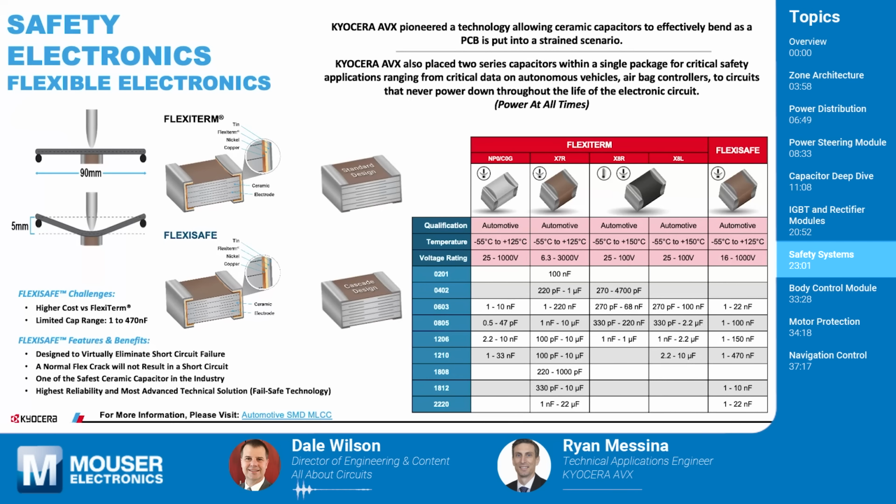So that's really interesting, Ryan. You've got two capacitors in series built into one package, and it's just a clever design. Again, another tool for people to have in their toolbox, particularly for these long-term, as you mentioned, high reliability applications, because failure as a short circuit is really catastrophic in a lot of applications. Correct. And that's what we're trying to mitigate here. And they do a really good job of doing just that.